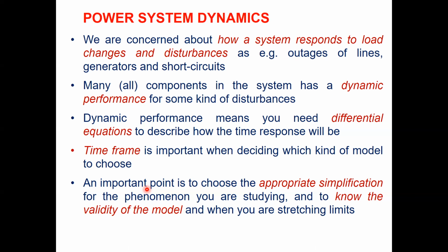That is for fault analysis. But if you want to perform some study for generator control, then transformer modeling is not very important. You don't need a very detailed model of a transformer, considering the saturation effect and so on. So depending upon what kind of dynamic analysis you want to perform, some level of simplification can be achieved.